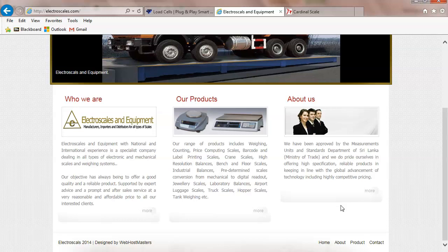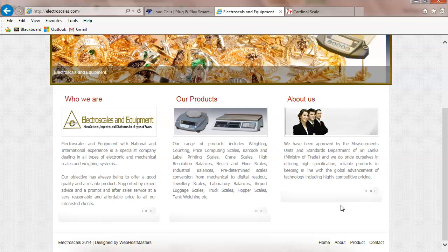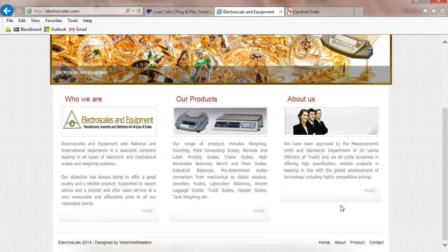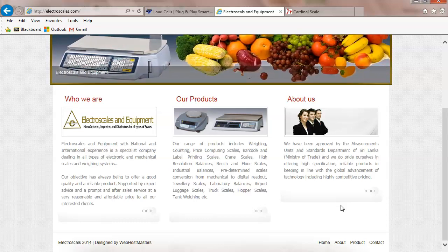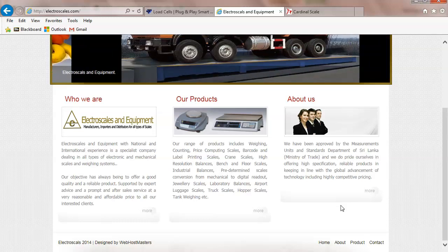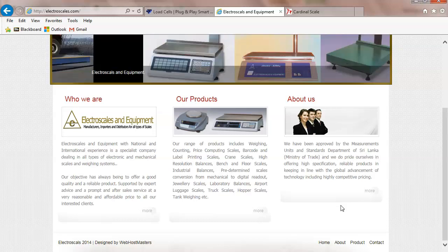Which is pretty neat. So yeah, the shield, but that's not a shield on the strain gauges. The strain gauges, that's the shield wire that's on the actual conductors themselves that's taking this millivolts. So these guys are going to give us millivolts out. And we called it millivolts per volt, and that would be what you excited them on, what we call excitation. But you see on just about all of them, it was 10 volts, right?